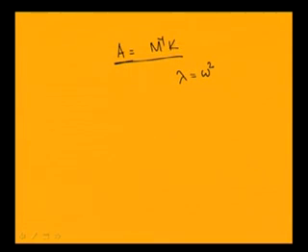Corresponding to these 3 normal mode frequencies, you will get 3 modal amplitudes, or 3 modal values, or eigenvectors. Corresponding to these 3 eigenvectors or normal modes, you can find the free vibration response of the system. For finding the free vibration response, use the superposition principle of the normal modes. Let us say you have 10 modes. In that case you can write the free vibration x equal to summation i equal to 1 to 10 of Ci phi i.